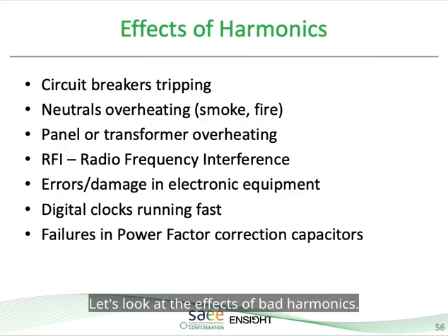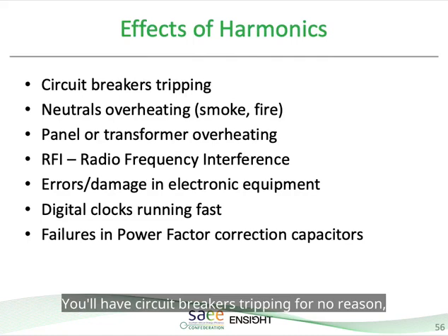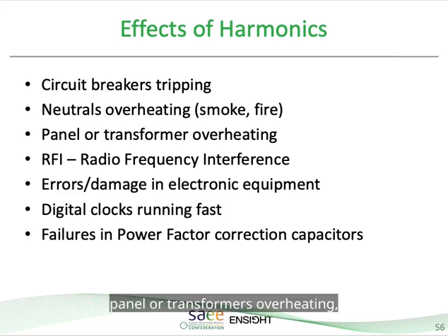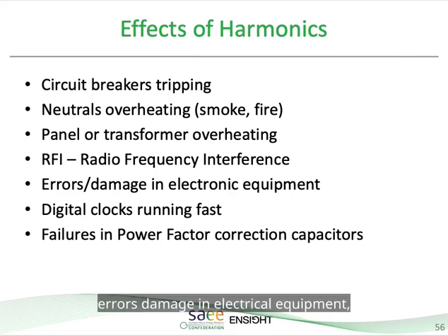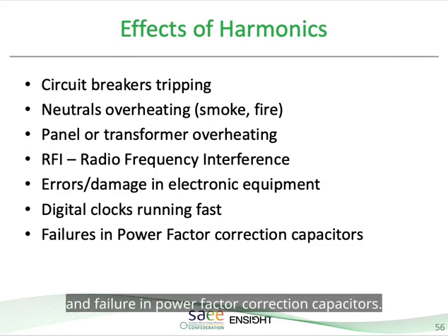Let's look at the effects of bad harmonics. You'll have circuit breakers tripping for no reason, neutrals overheating and potential fire hazards, panels or transformers overheating, RFI (radio frequency interference), errors and damage in electrical equipment, digital clocks running fast, and failure of power factor correction capacitors.